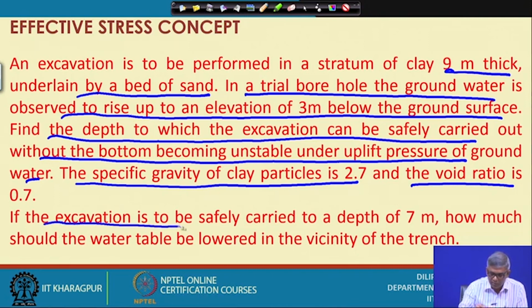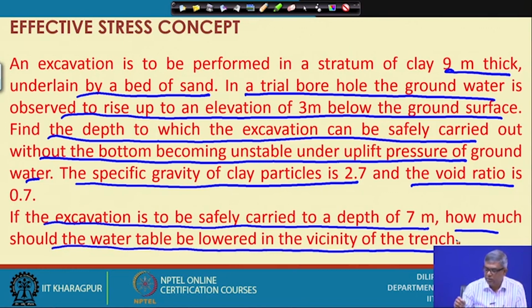If the excavation is to be safely carried out to a depth of 7 meter, how much should the water table be lowered in the vicinity of the trench? So, I have mentioned that by lowering the water table, sometimes effective stress will be increased, that is the thing required. So, that requirement is also mentioned here. So, I will sketch this one.